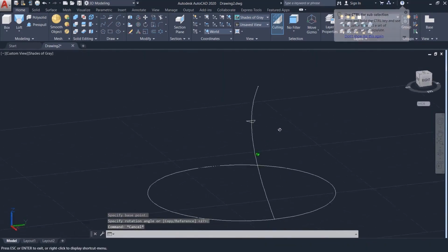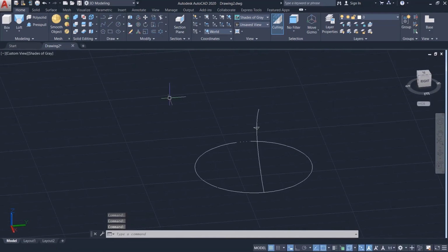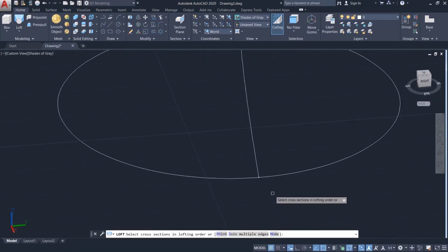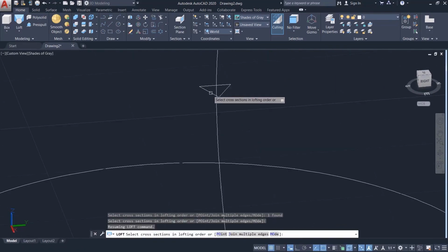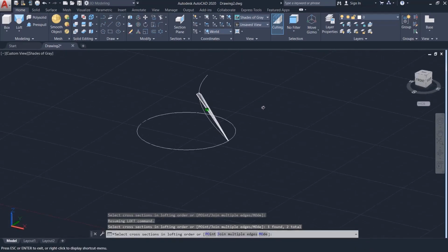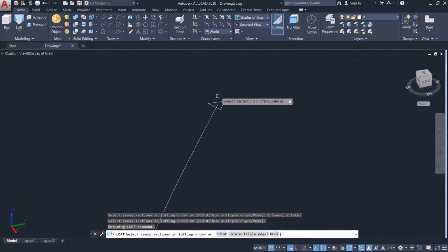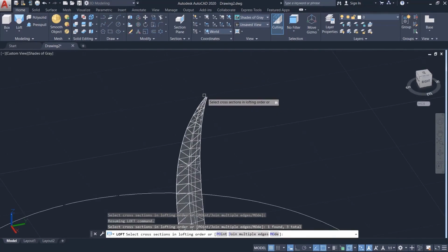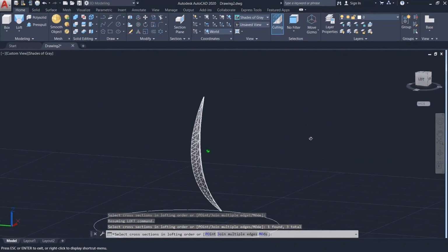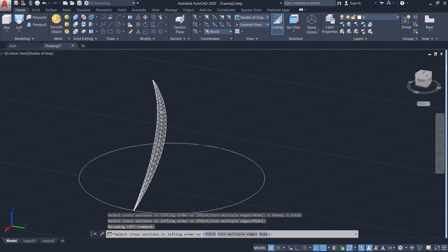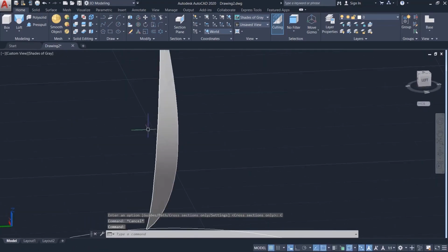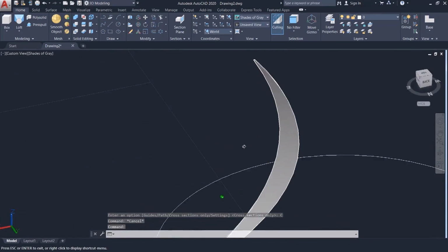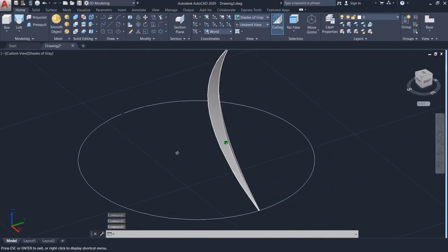Okay? It's that simple. Now, what we need to do is select loft. The bottom triangle, then the middle triangle in order, and the top triangle. You see, it drew this shape. Enter. Just cross section only, and that's it. How easily and beautifully my object was created.